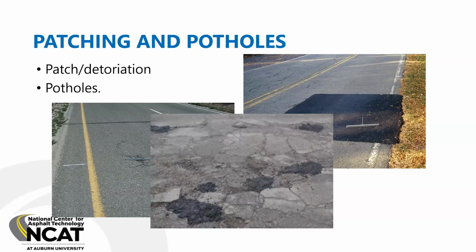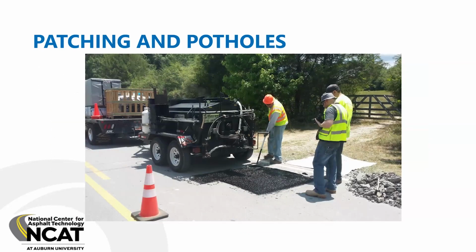And then that's some really ugly patching and some really advanced deterioration of pavement that can't be patched. If you have a very challenging pothole, this is a picture of a pothole that we repaired over on Lee Road 159 when the water line broke beneath the pavement, and that is a highly polymerized mastic patch. It's sort of a coarser mixed version of the patch that I showed you from Minnesota previously that we had used on that longitudinal crack.